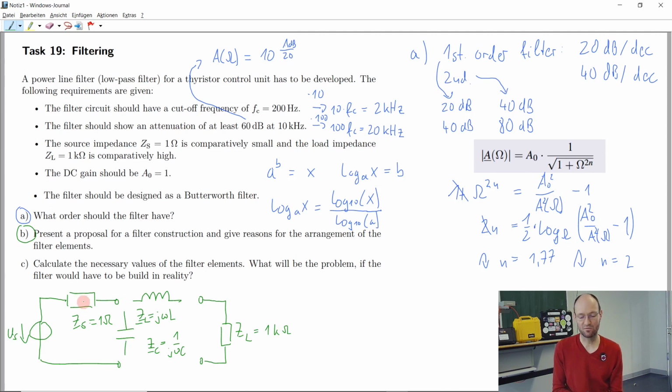I think it is better for the high frequency rejection. Low impedance here. We have then in comparison a rather high impedance here. And whatever gets through would need to go into this high impedance load, but it could also go over the low impedance capacitor. So from my point of view, it would be more feasible, and as said, we can try it out later on.